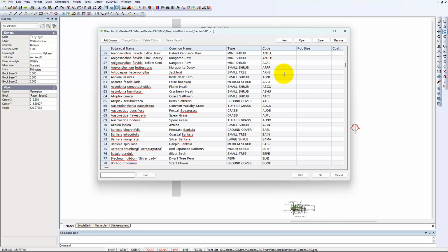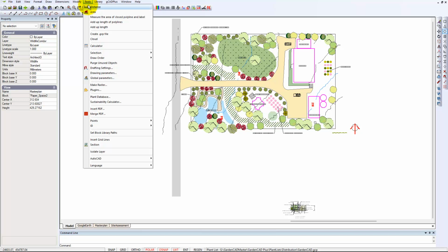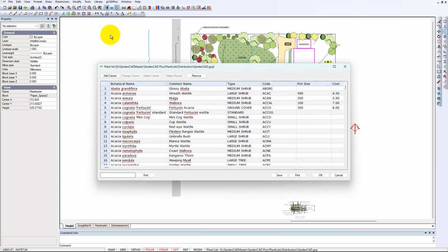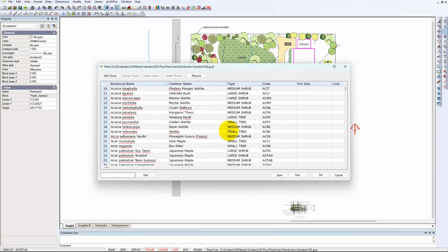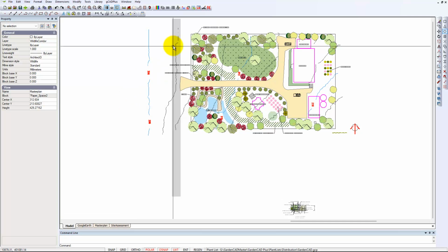These files are known as GCP files. It is possible to generate a GCP file from scratch. You just go to Tools and create a GCP file here, and if I click on it, it's currently going to this one. It picks up the existing one, but if we remove that, let's do that.